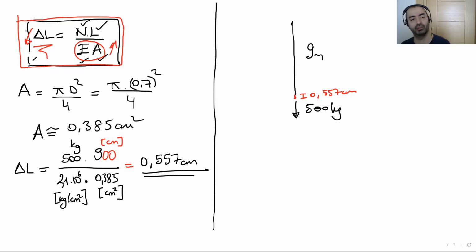So everything is around these two equations. One is the stress equation, stress equals N over A. The other one is delta L equals NL over EA. This is the second equation. If we know all these equations, I guess you memorize them. That's it. It's easy if you understand what you are doing. Otherwise, it's not easy to use this equation, even if it's really basic. Let's do another example.